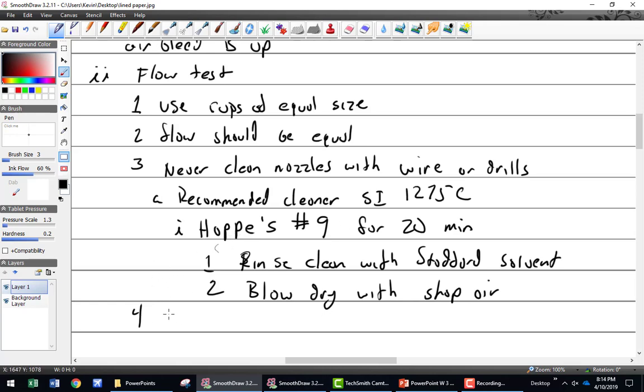Anyway, you think you did it, so you're going to put it back in. So these are a pipe thread. So pipe thread is sealed in what manner? What makes the seal on pipe thread? Cuts into it. It's a conical shape. So the tighter you make it, the more it wedges itself in there, and the tighter the seal. Well, you don't want a fuel leak, right? So smash it good. If a little tight's good, a lot's better.